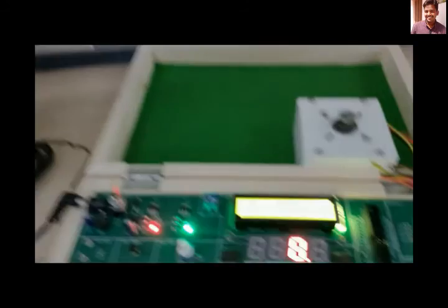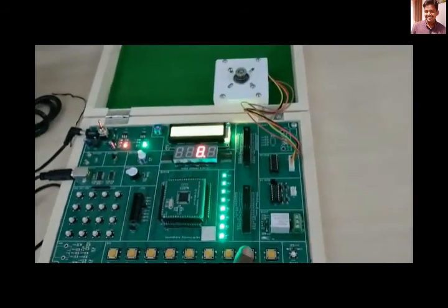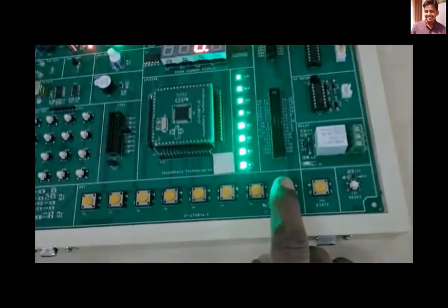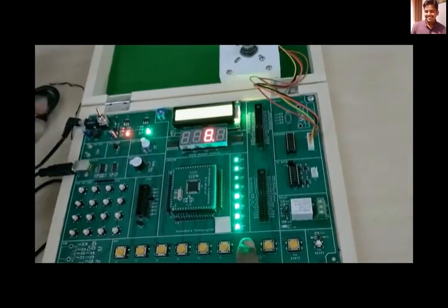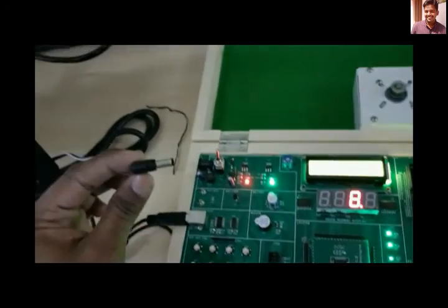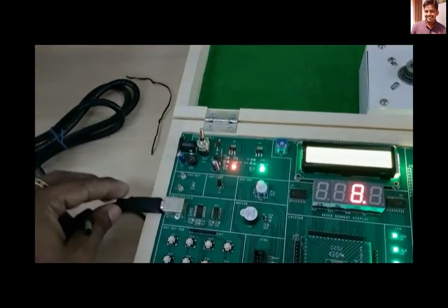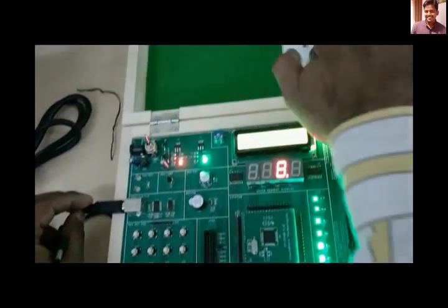Once this is done, as all of you know, in the logic we have explained, we have two switches, one to run the stepper motor in the clockwise direction, the other to run it in the anti-clockwise direction. As I told you in the stepper motor experiment, we need an additional power supply to run the stepper motor, because the USB cable that we have connected, even though it is supplying power to this LPC 2148, is not sufficient to drive the stepper motor. Why? Because a stepper motor consumes more power.